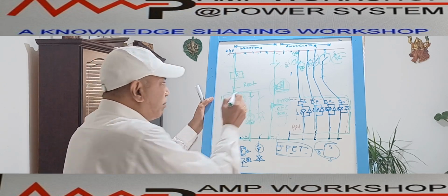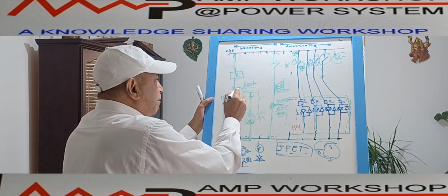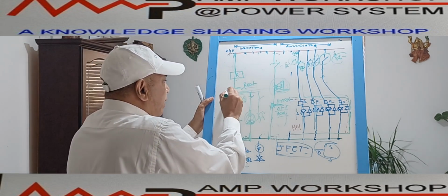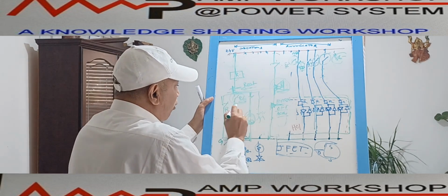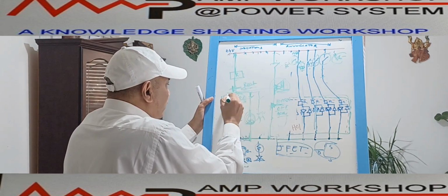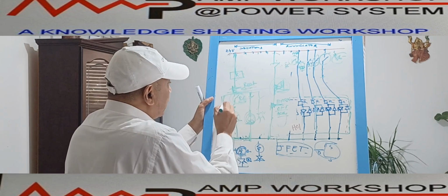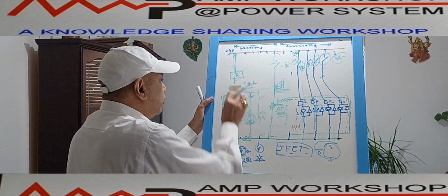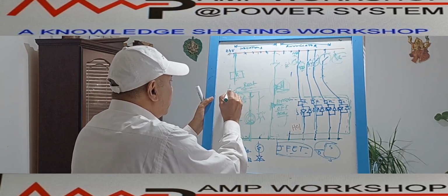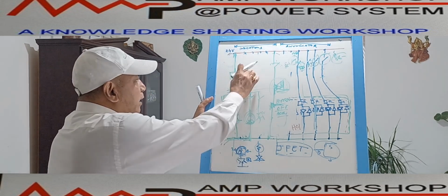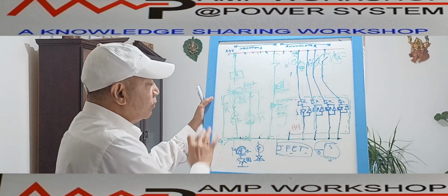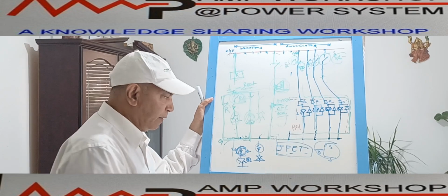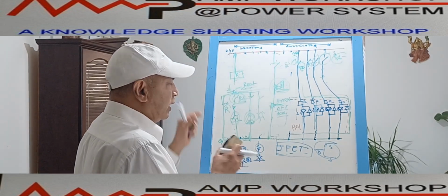So what I have to do is press the reset button. The moment I press the reset button, though this contact was NC, it becomes NO, and if the fault is clear, current cannot flow through this and the relay will drop out. This becomes normal, so the circuit becomes normal. This is how, in the old days, we used the horn in this way, but nowadays all this is not there.